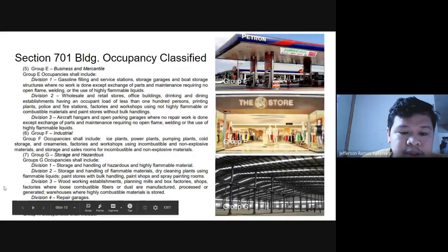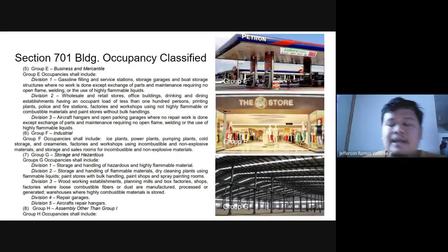And there are four divisions for different hazards, such as toxic materials that must be isolated. So in environmental engineering, you will study how to store and dispose of hazardous elements. For example, muriatic acid needs to be stored separately from combustible materials, because muriatic acid, when exposed to fire, can be toxic. It can release sulfurs, so you can't breathe. So the civil and environmental engineers work together on that. Even in waste disposal, okay, that's a requirement.